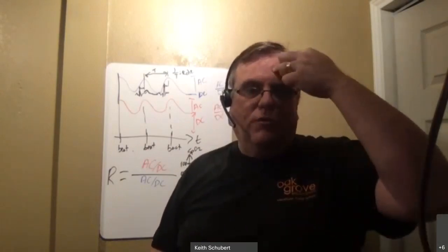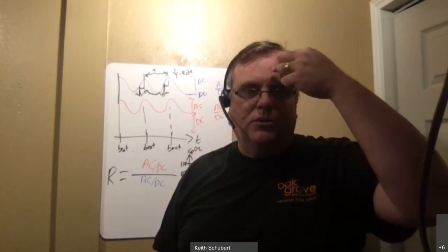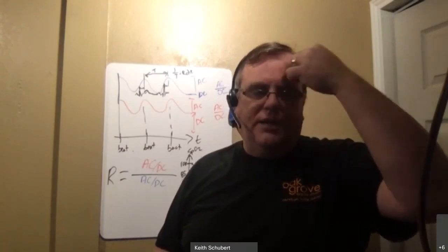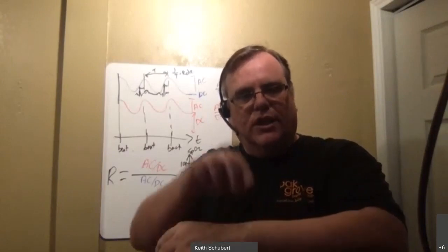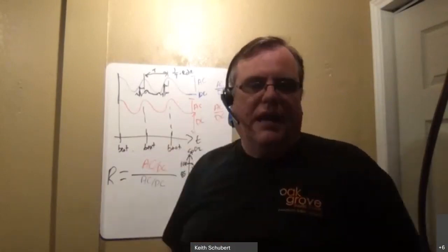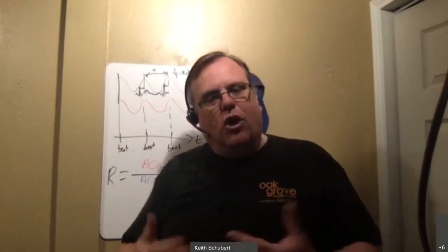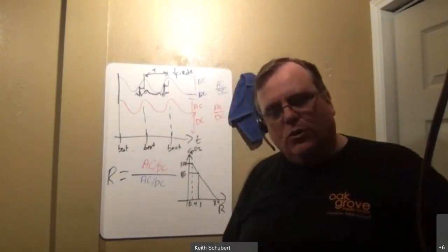So people will actually do reflection versions of pulse oximetry by putting a sensor on the head and bouncing light off. That's essentially what's being done by the watches too, because you've got bones in there. So they're bouncing it off the bones back to the sensor. And so very often green is picked for the reflection versions of these.